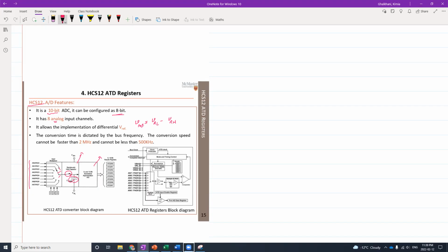What do I need to do in here? There is an external crystal, which is this guy. I'm going to have some crystal oscillator in the microcontroller. Some of these oscillators are built in, but those are not fast enough. But the external one, this is the oscillator. Let me draw it bigger for you. Right?